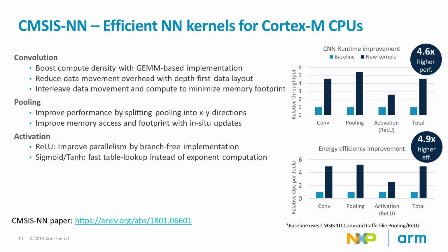There's some gain using the FPU, but the FPU does not always come with advantages only, as you have to stack larger stack segments on interrupt entry and other things. So fixed point math is the preferred choice of an embedded developer wherever feasible. In the case of the keyword spotting neural network, a 16-bit fixed point type from the CMSIS DSP library shows the best ratio of memory usage and performance, while still having the accuracy almost not impacted compared to the float type. CMSIS-NN provides specially optimized variants of the required functions underneath that add up to the overall performance improvement of 4.8 times faster than the standard implementation.